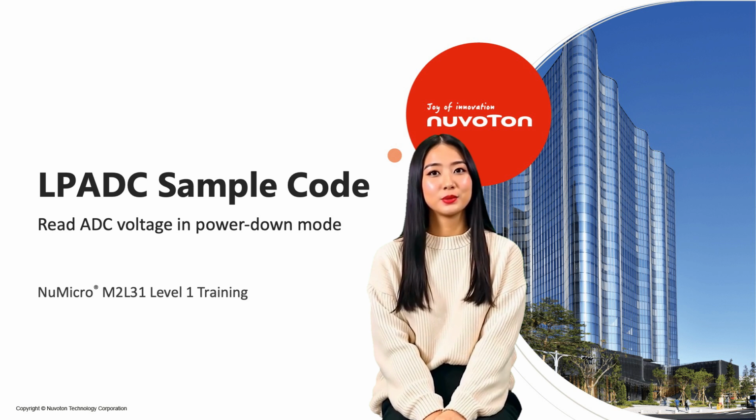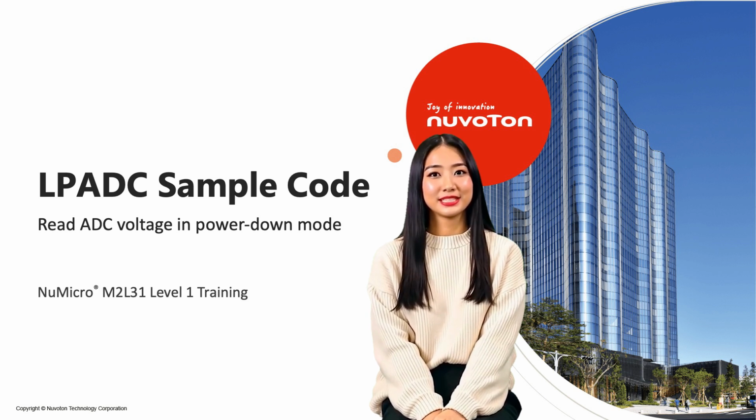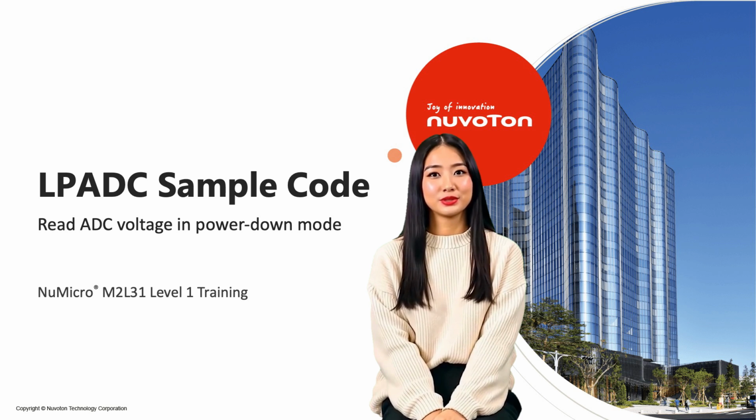In this video, we're going to introduce a low power ADC example. The main focus is to show how we can use auto operation mode to let the ADC automatically sample voltage data by hardware in low power mode. With this approach, even when the system enters a low power state, the ADC can keep running continuously without needing the CPU to wake up. This makes it a very practical solution for low power sensing applications, where saving energy is critical.